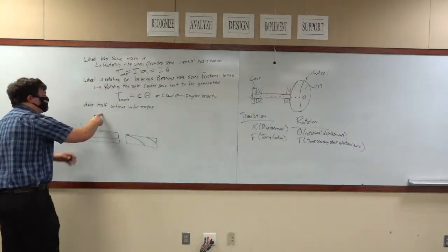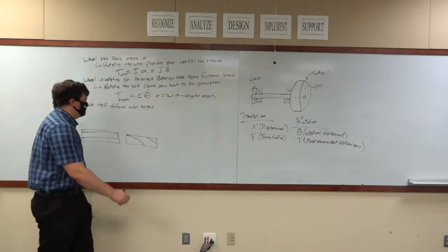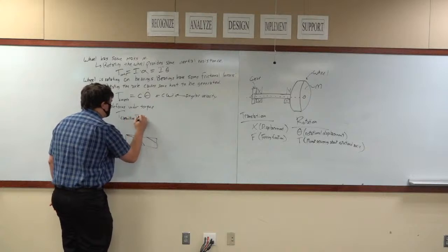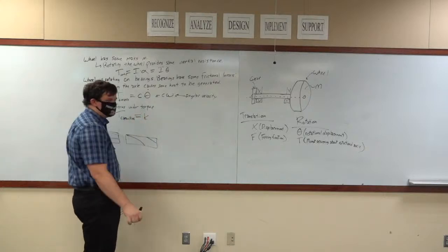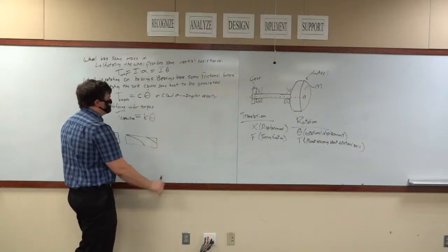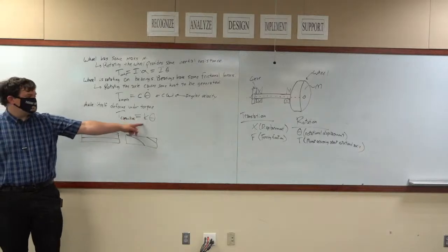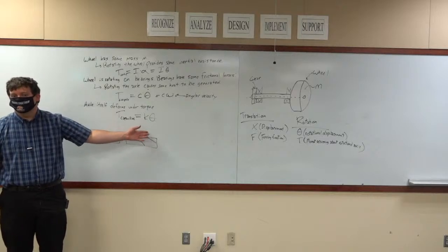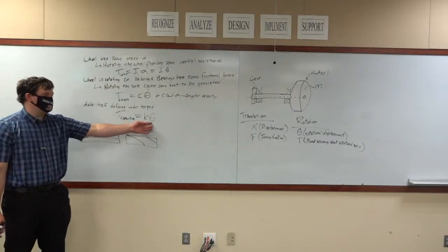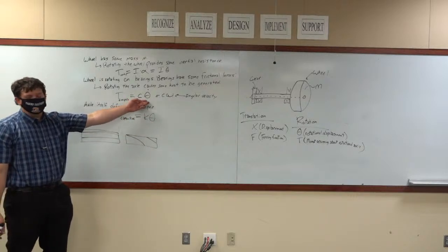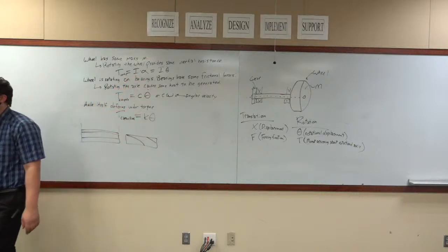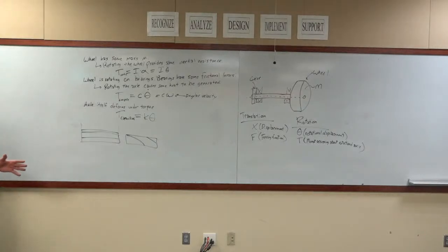When you apply a torque, the material itself deforms. And when that happens, your capacitive torque occurs when you have some spring constant multiplied by some angular displacement. This equation looks very similar to K times X, which is the equation for our spring. It's just instead of using X, we're now using theta. This equation looks a whole lot like Cx dot. This equation looks a whole lot like MA. That is not unintentional. The formulas for these are identical.